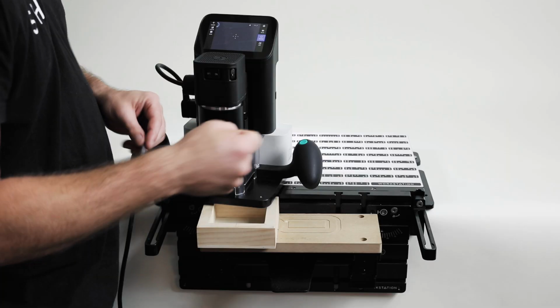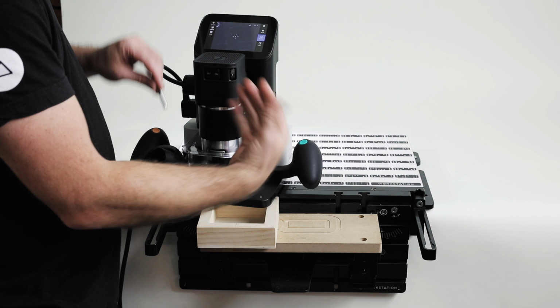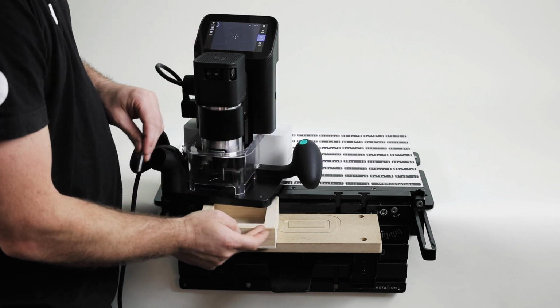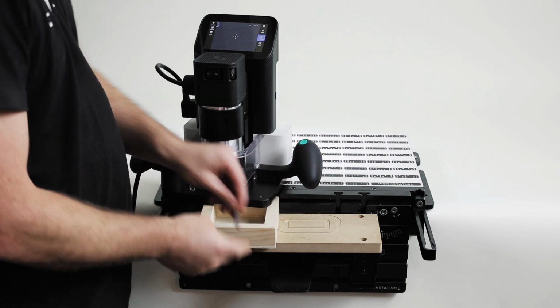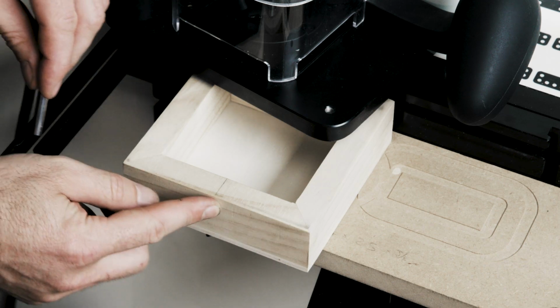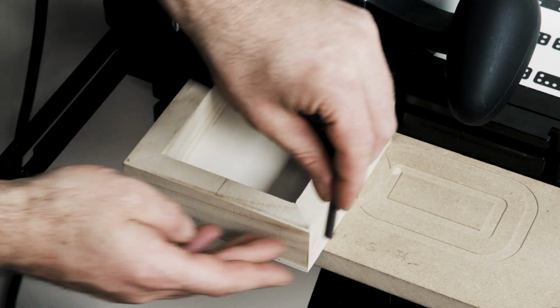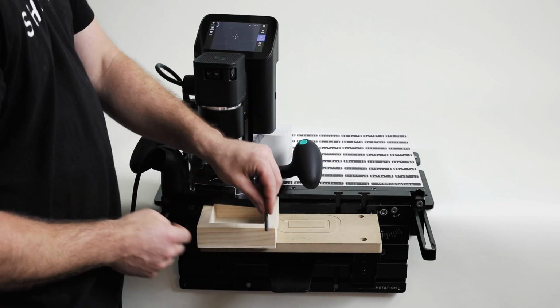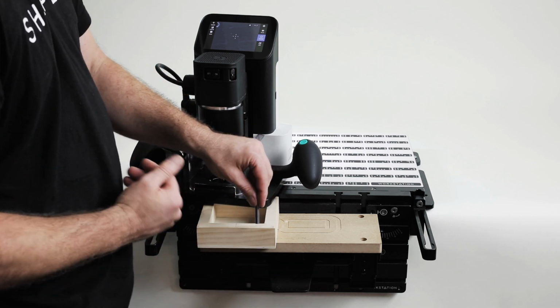The key there is a light touch. We don't want to push hard. We don't want to introduce any deflection. We don't want to squash our wood. Pressing too firmly will cause the mechanism to deflect, and it will cause your wood to compress. That will produce a poor quality grid. It will be slightly offset. So the key is to come up very lightly and touch the edge. It's a precision measurement, keep that in mind.